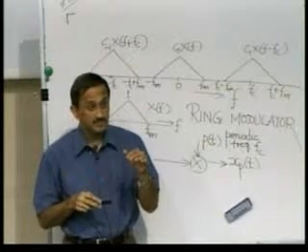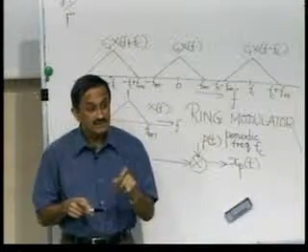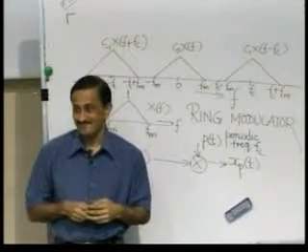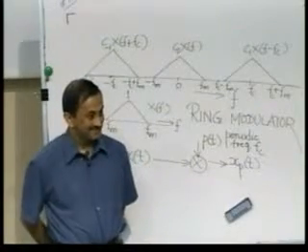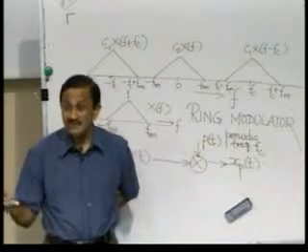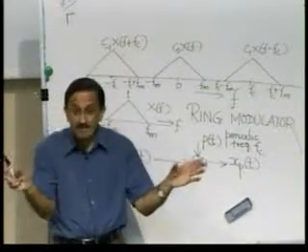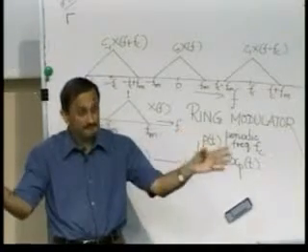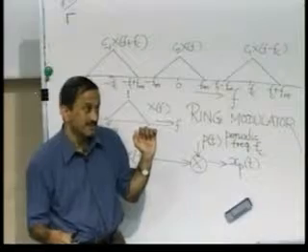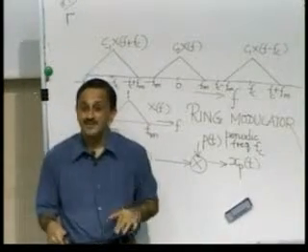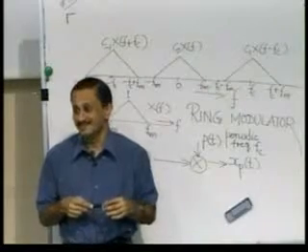The second advantage here is that I don't really need to construct a waveform of frequency equal to the carrier frequency, but it could be a sub-multiple. So, even if I want a carrier at 3 megahertz, I could construct a periodic waveform of frequency 1 megahertz. And if I have a Fourier component at 3 Fc, then a replica of the spectrum appropriately shifted occurs at 3 Fc and minus 3 Fc, and that can be extracted as the modulated version of this signal with a carrier frequency of 3 times Fc. Two advantages result when we exploit aliasing. So, aliasing can actually be exploited to the advantage of the engineer.